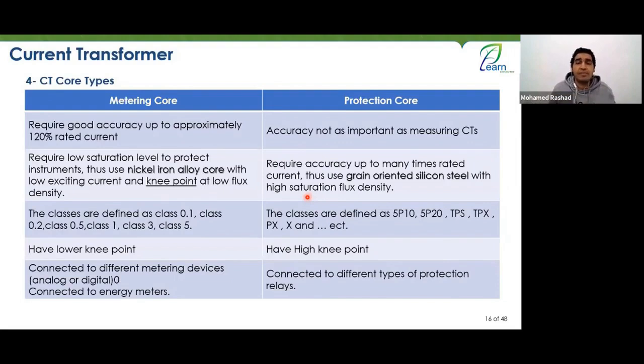Of course, I gave you a simple example with overcurrent, but you also have differential and distance protection, which includes zones of protection, and you have directional earth faults and a very large set of protection functions, and each protection function is different from another protection function.